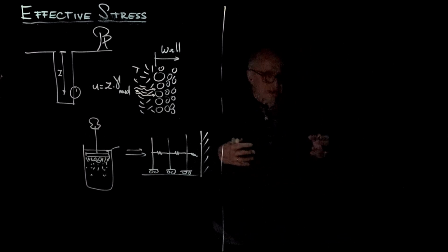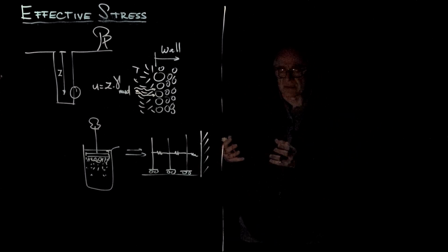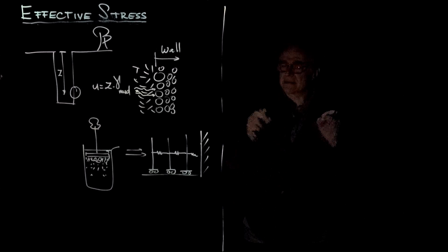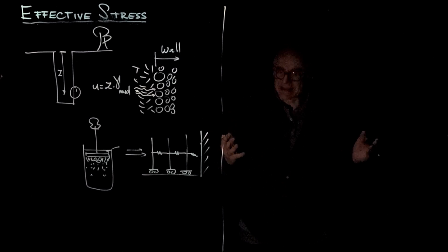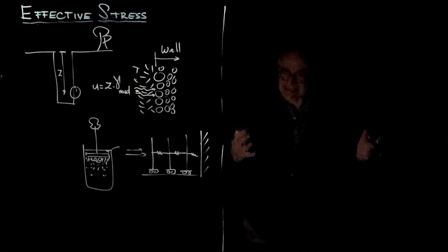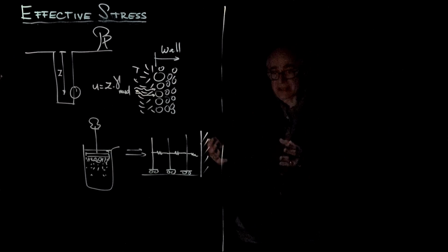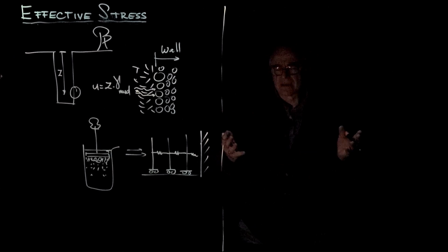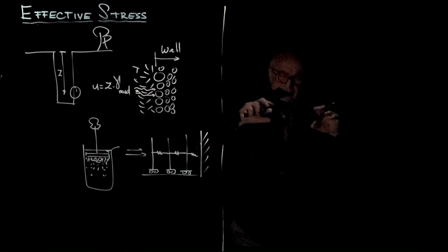And hydraulic fracturing has been argued as a mechanism for the failure of dams, and is a critical mechanism, for example, for enhanced oil recovery, for gas recovery from shale gas. So what is it? There is zero tensile strength in a sand. So it cannot be that we are overcoming the tensile strength. This is not a tensile strength failure, because there is no tensile strength in a soil without diagenesis, whether it is a clay or a sand. So what is hydraulic fracture?